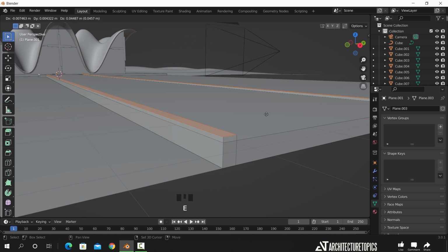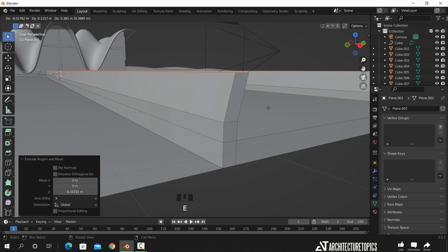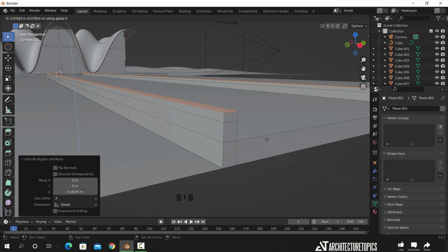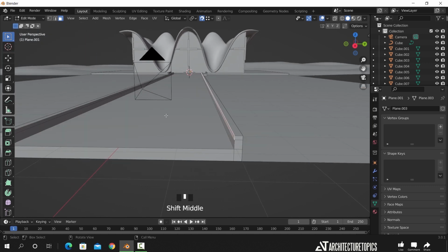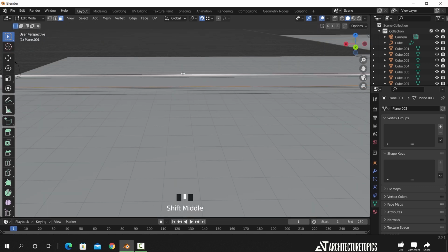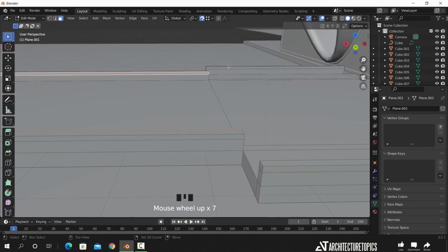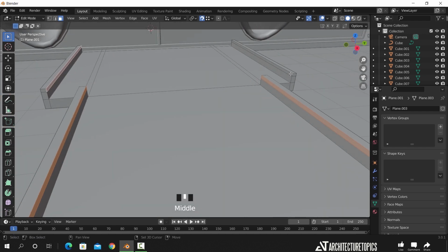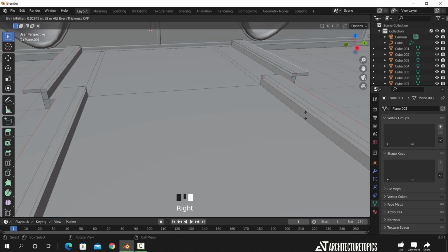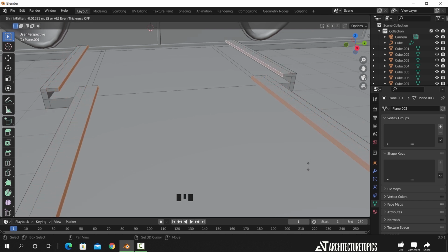Once we selected those four faces, we can extrude them up 2 times, and again after that extrude the upper parts to inside. Now with those upper faces, we can hit the right mouse button, and extrude them along normal to inside.